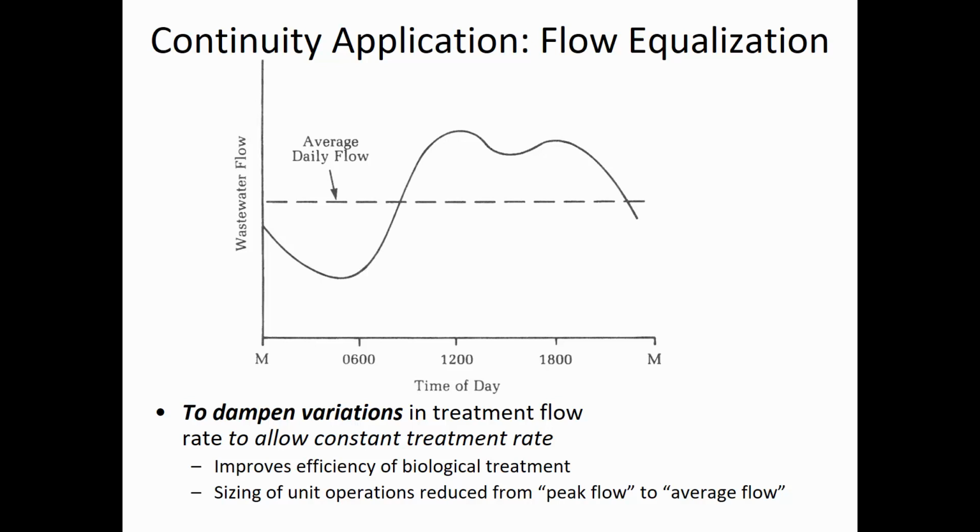So sizing of ponds doesn't just apply to wastewater treatment plants. It also applies to stormwater from developments like the new Tanyard Station development that they're doing over on Route 60. That used to be an undeveloped area that, generally speaking, infiltrates water into the soil more than roof area, more than pavements. And so anytime a developer in West Virginia does a big project like that, the state has regulations that they have to put in some sort of a way to capture runoff, because you don't want to make flooding any worse than it already is in the streams and other water bodies that receive the runoff.